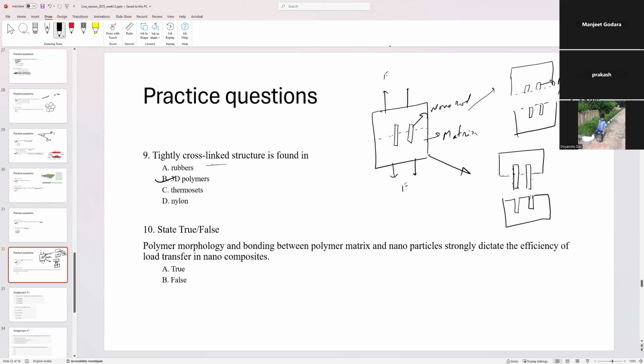So here there was energy required to break these nanoparticles, and these nanoparticles as the reinforcement are tougher materials which require more strength to break. Whereas in this case, your nanoparticles were not broken, and just were pulled out. So this matrix-nano interface is not strong, it's weak. Matrix and nano interface is weak.